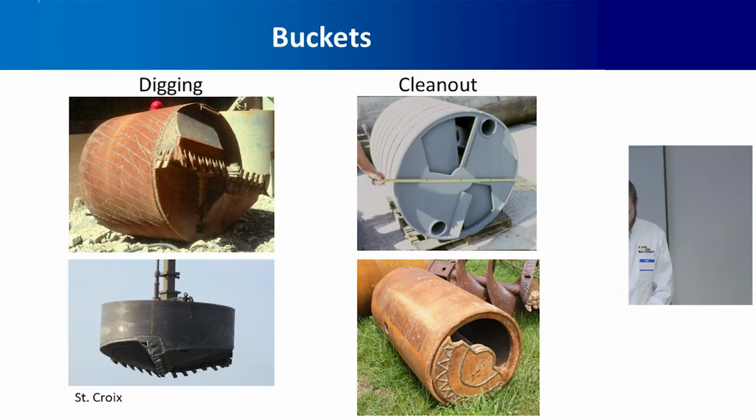Digging buckets are used because loose granular materials like sand or gravel don't stay on an auger very well. So you can use a digging bucket. It basically has similar teeth to an earth auger, but it captures that material in a bucket, and it's got some kind of flap doors on the mouth of that cutting part to trap the material inside the bucket.